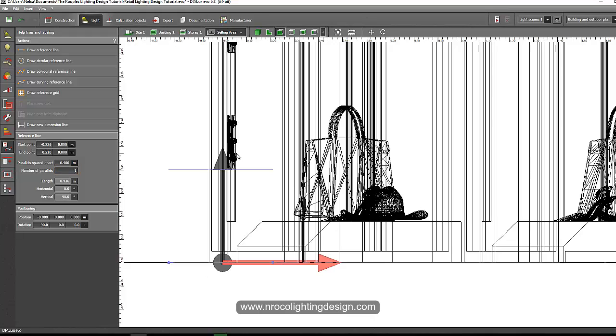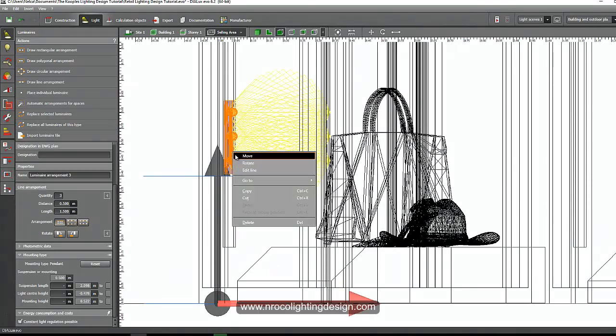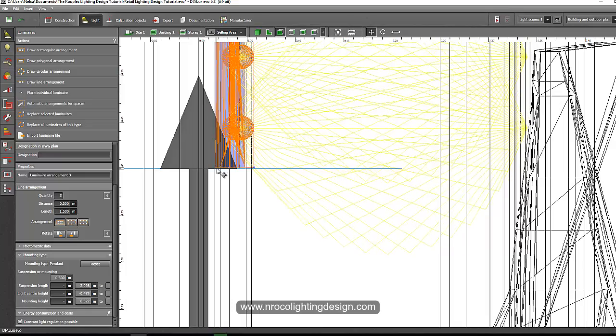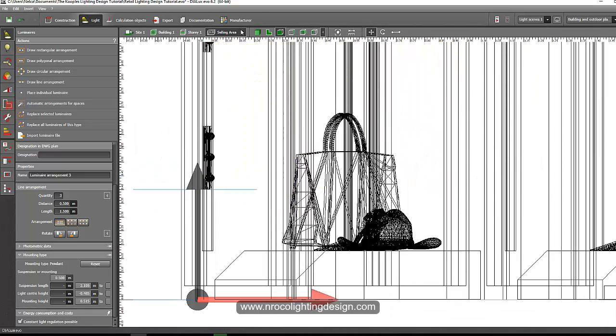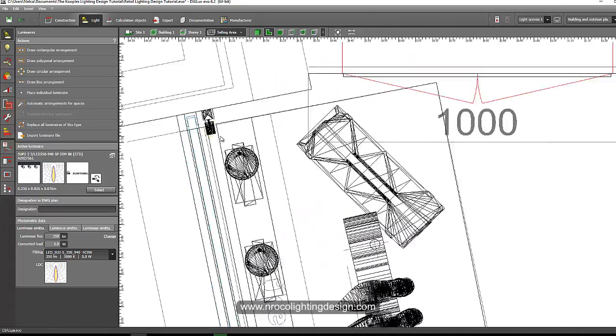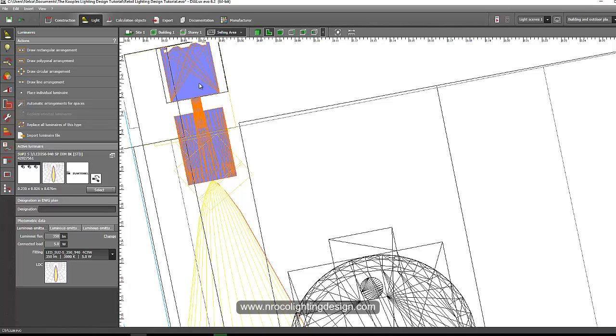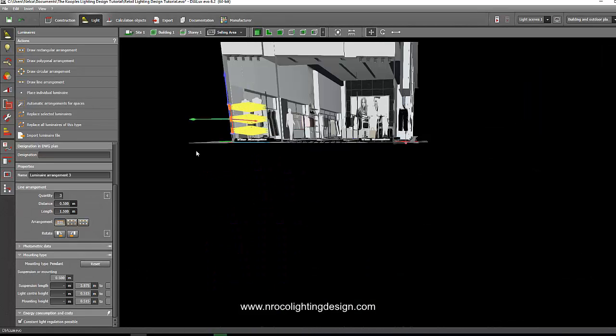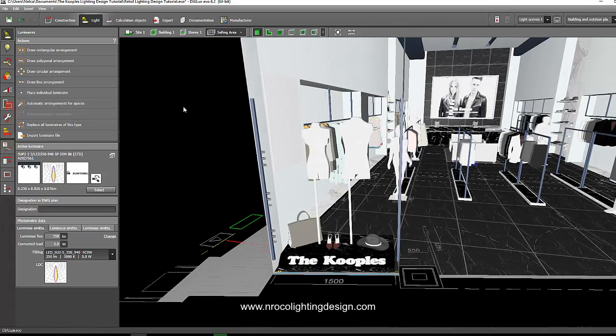Now it's there. And then let's move our luminaire to this 0.4. Put it down. Okay, so let's go to the plan view and double check it. Yes, it's properly placed now, and the height is 0.4 from the lowest bottom, from the lowest fitting.